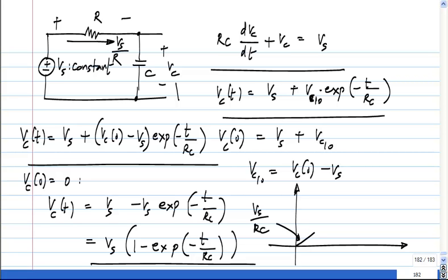If you differentiate it, do you get that? At the initial instant, you do get that, right? So, you get plus Vs by Rc. So, that sanity check is also satisfied. But as the capacitor voltage increases, what happens to the current? It decreases. Because this voltage is ramping up, the current will reduce.